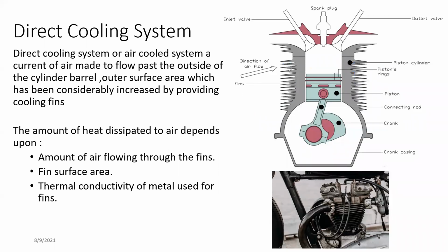Okay, so I'm pretty sure you guys have a good idea how this works. But one thing I need to mention here is that in these engines, the oil cooling system, so the oil inside the engine, is playing a huge role, because since there's not much water cooling happening, in addition to the air cooling system, the oil system or this lubrication system helps a lot in cooling the engine itself.